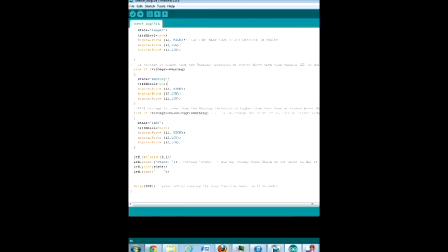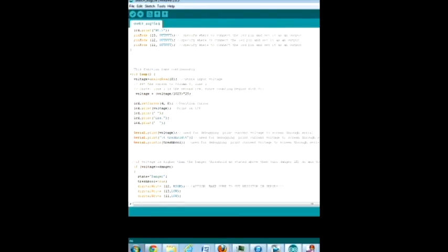It also set a Boolean to true, which also changed the LCD state to warning, so it would show warning on the LCD. And if those two conditions weren't met, then we had an else statement, where the voltage is lower than the warning threshold or higher than 0, then as stated above, the safe LED would turn on, and you would see a state of safe on the LCD. This was the main function of our microcontroller for the Arduino Uno software.